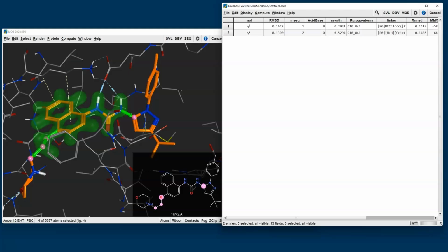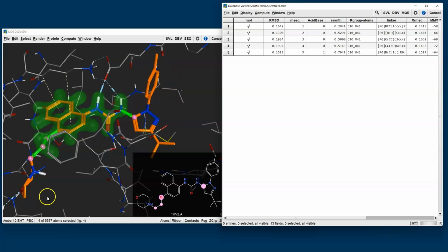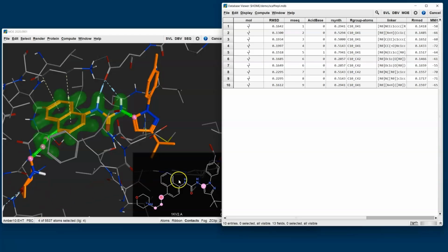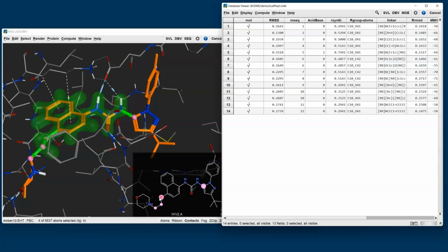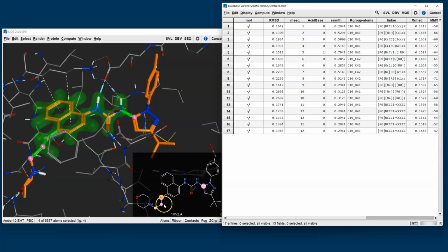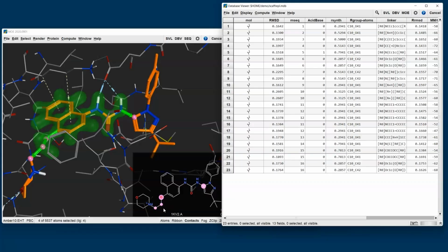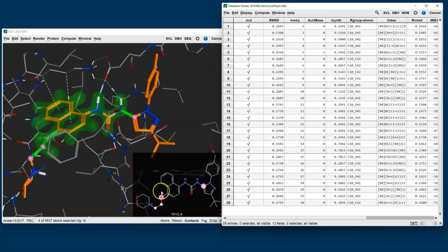Mo is now searching for scaffolds to replace the atoms that we see in the halo between the bond vectors, whilst preserving the geometry of the fragments that fall outside of these attachment points. This time though, we're effectively running 3 queries, the first replacing the scaffold between this point here and this point here. The second run will do it from here to here, and the third will do it from here to here. So effectively 3 queries in one. We could be running 3 separate scaffold replacement queries, but this is a much easier way to do it using the scaffold replace R atoms.